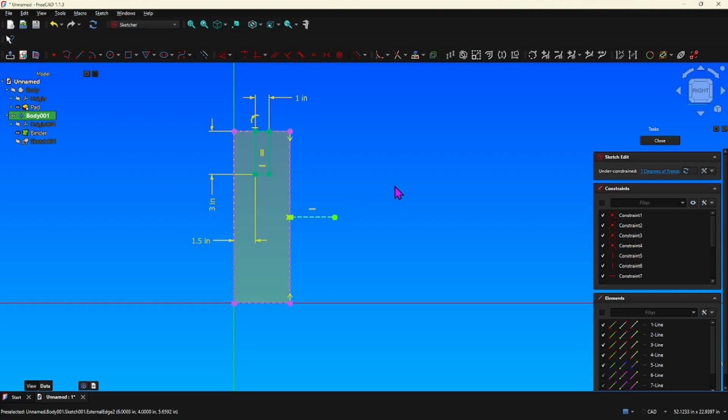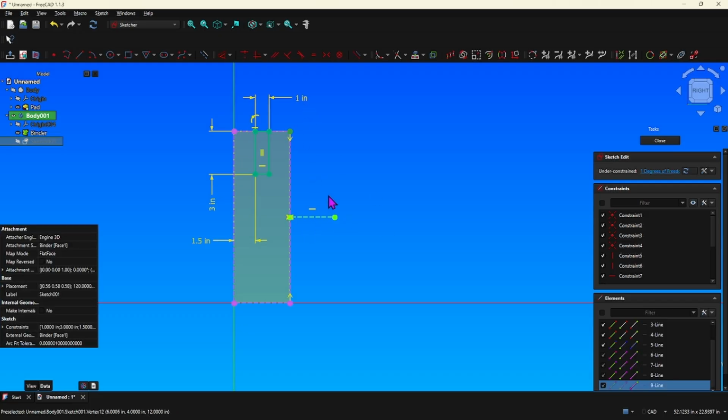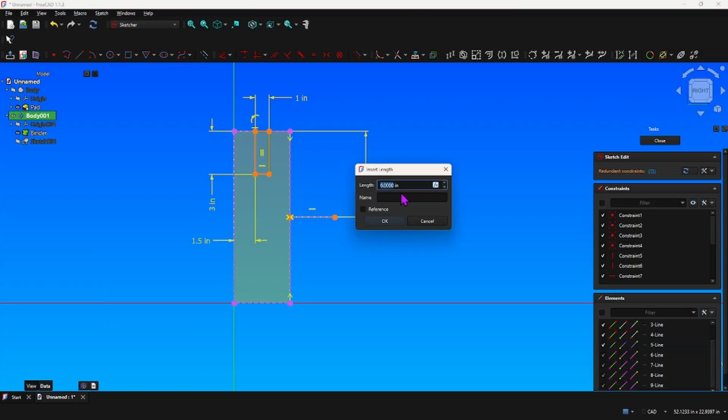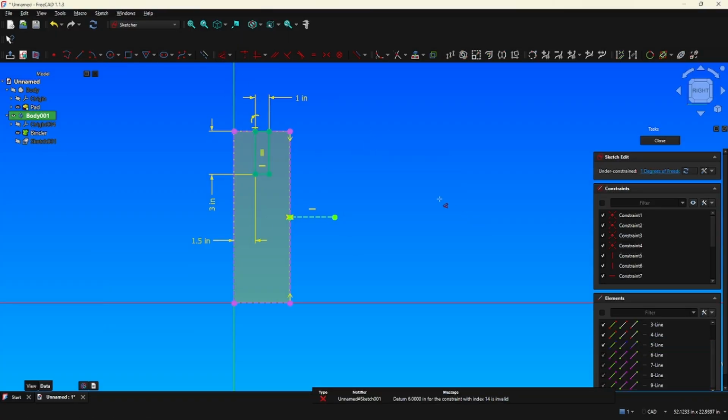So most of the time, it's better to do the math in your head. But I can see where if you had a length, let's just say that length was like 11 and 3/16, and you'd be scratching your head to find out, well, what's the midpoint of that? What you could do is just do what I just did here and just do a quick reference, like, okay, from that point to that point, now that I grab the midpoint, reference it, and oh, okay, 6 inches, boom, and then write that down.